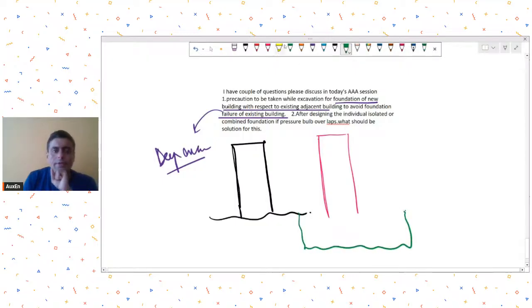So when you start excavating, you have to be mindful that this will also have footings. It depends on the soil strata, first of all. If your strata is quite hard, then you may not have failure of collapse. If it is a strata which may undergo collapse, then generally in the geotech report, they tell you what slope to maintain, how to manage deep excavations.